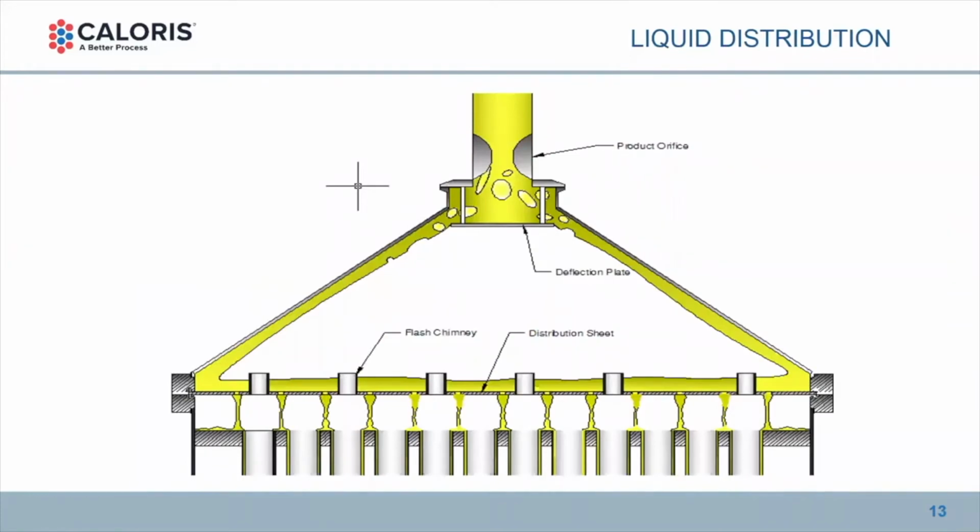So those were the first three bullet points, as I went through my initial list there. The next one was liquid distribution. And we've done a number of rebuilds on evaporator systems modifying the liquid distribution. And this is critical to good functioning performance of any evaporator system. You want good wetting of all of your heat exchanger tubes, particularly if it's a falling film evaporator, as is shown here. So we've got our feed coming in the top, and we've preheated it to above boiling temperature,